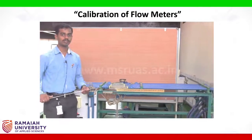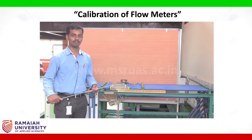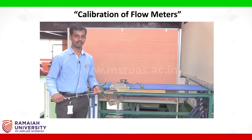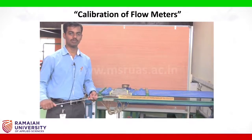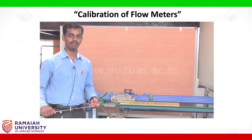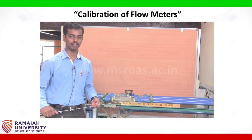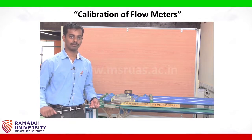There shall be some errors in the flow rates between the rotameter reading and the venturometer reading. We shall calculate the errors of each individual flow rate, and then we can calculate the correction that is required for the rotameter to be calibrated according to the venturometer flow rates.